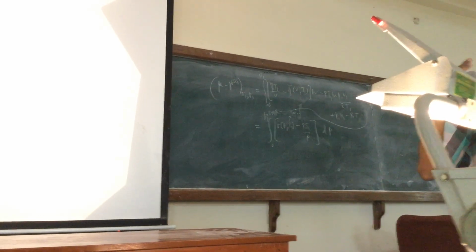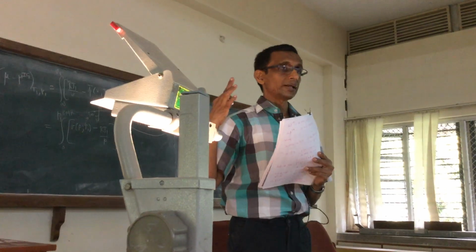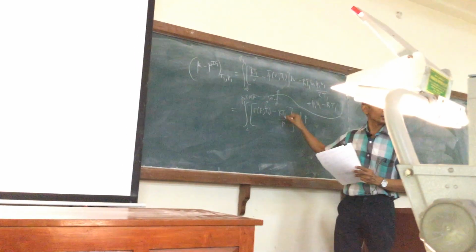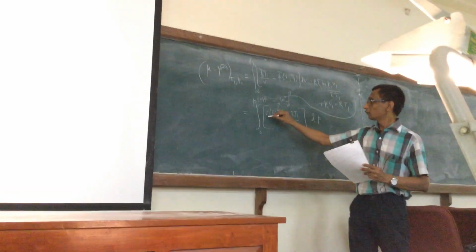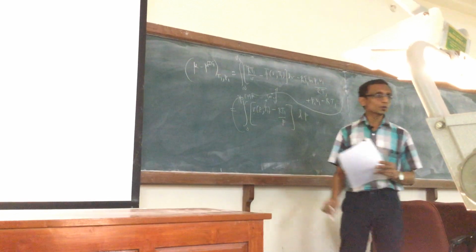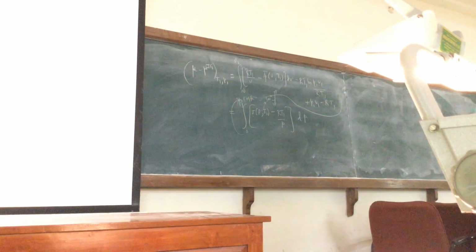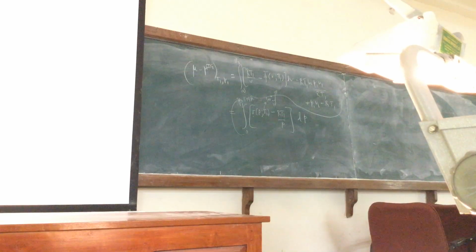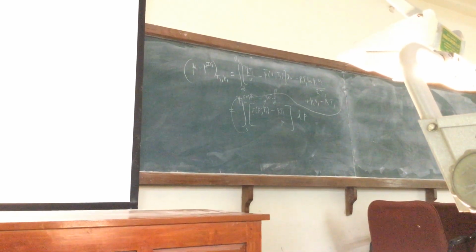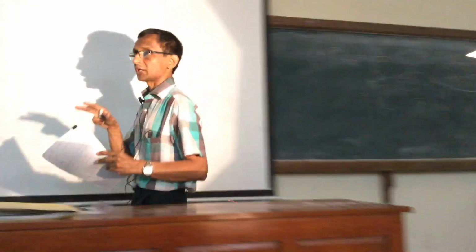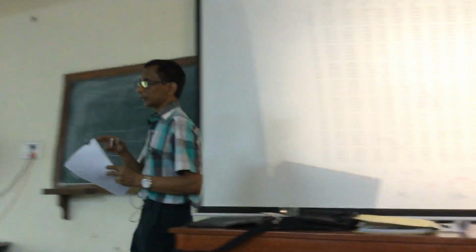You have to go to the 300 degrees centigrade superheated table and calculate; RT1 by P is very easy. The integral is over the entire range from 0 to 8. Now obviously we can't get the value at 0, it is obviously RT by P. But what pressure you would choose would depend on the lowest pressure available in the tables.